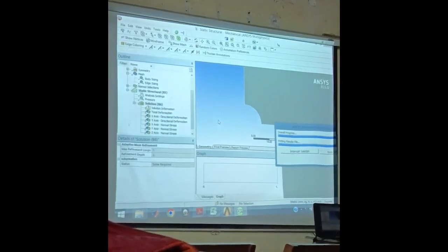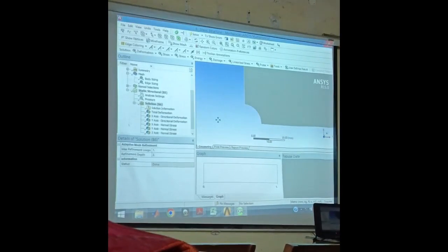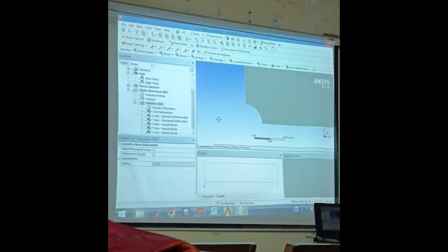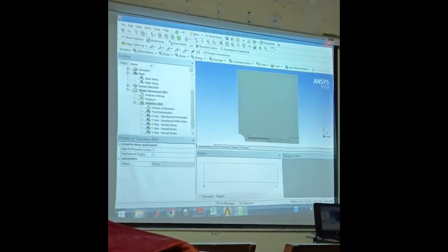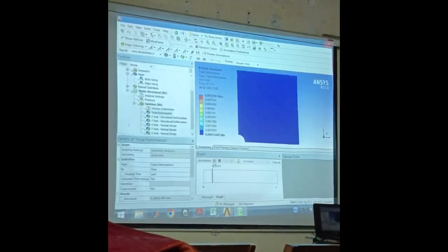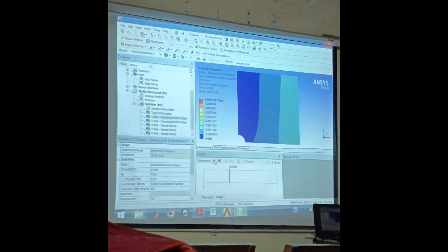So what I am expecting is, if I have 10 MPa inside force, then the vertical top direction is supposed to be 3 times 10, 30 MPa. And the right side here is supposed to be minus 10 MPa. Let me check what value we got. Deformations look fine. That way it should be. Yes, deformations look fine. Y deformations. Contour is okay. Now x-axis normal stress.